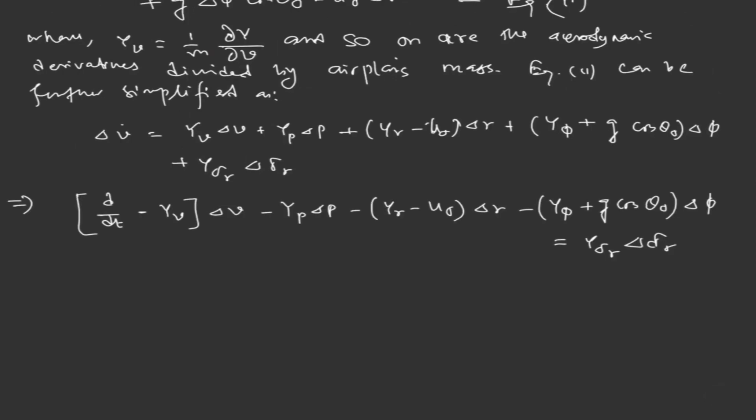If you notice, these equations are linear because the coefficients of all the terms are scalar components, not time varying, or we can say time invariant. And this system we can also call a linear time invariant system because all the coefficients of the equation are time invariant. If you notice this equation, it will be very clear, because these terms are basically what we generally get from wind tunnel testing for the given flight conditions.